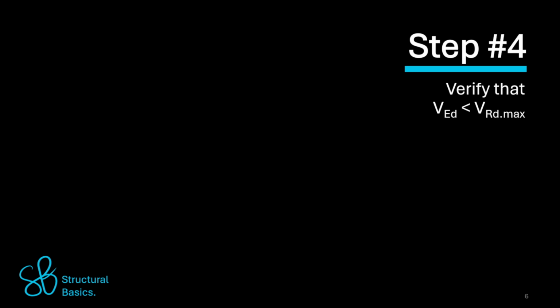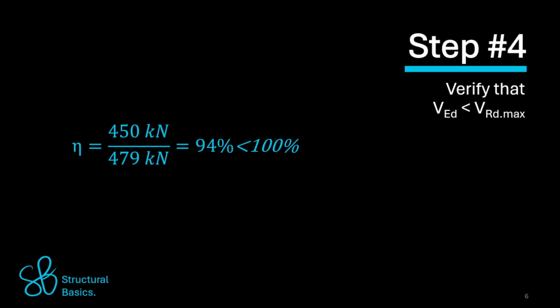In step 4, we verify that the shear force is smaller than the design shear resistance with shear reinforcement. A design shear force of 450 kilonewton and a shear resistance of 479 kilonewton leads to a utilization of 94%, which means that it is verified.